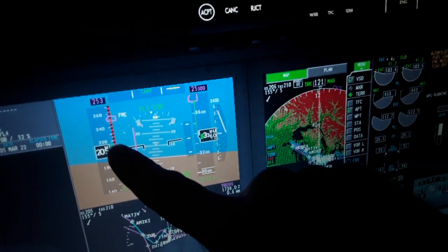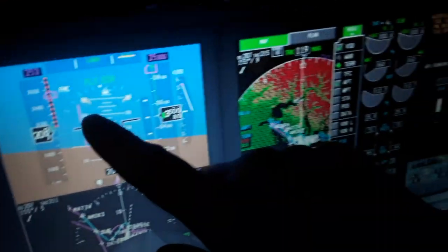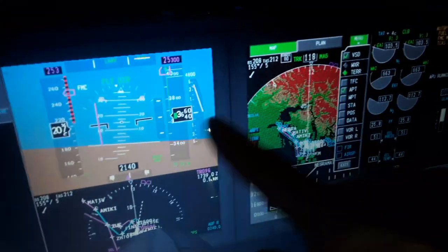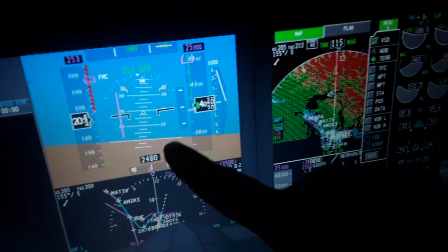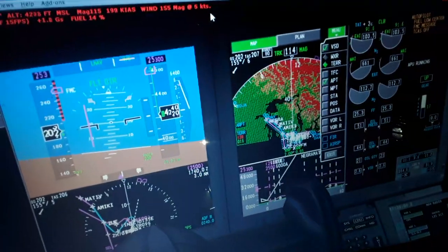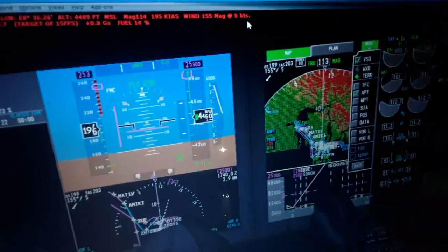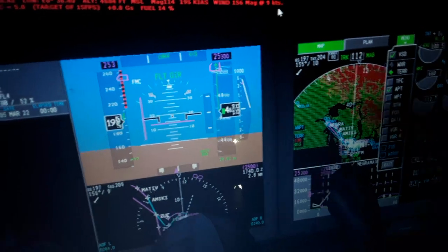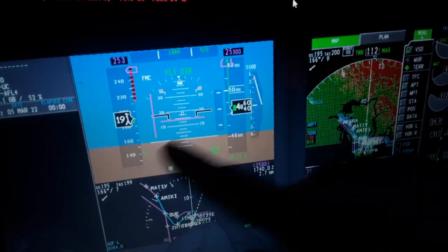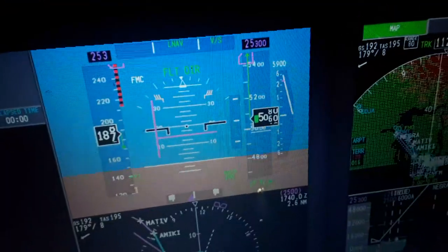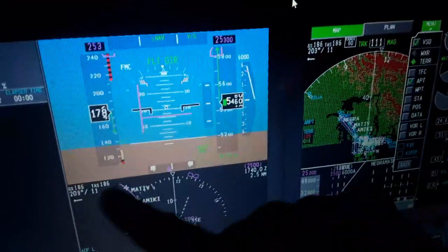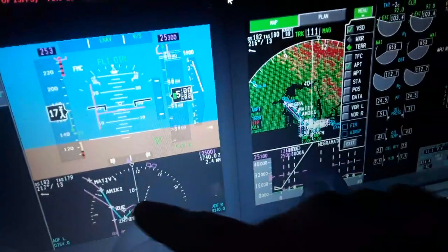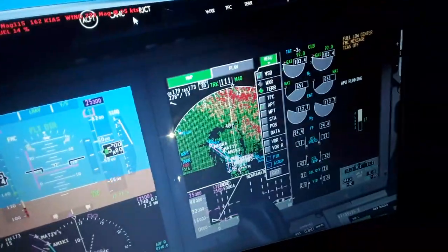The airspeed 205 knots right now. The engine's indication also, you can see the climb rate. So we are 2,300, 2,400 above the ground, 4,000 above the sea. The pitch attitude 20 degrees. The airspeed 195 knots. The stall speed here, you can see the trend lines also of the speed and the altitude. We climb with 6,000 feet per minute. The wind direction, speed, the flight plan we created here. Also you can see